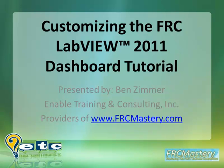So in summary, in this video, we talked about how to modify the robot project to put whatever information you need into the dashboard data type. Recall that in order to do that, you needed to modify the data type def, as well as make changes to the actual dashboard data sub-VI, which is writing that information in. And then we learned how to create the dashboard project and make the necessary modifications there. First, to refer to the proper data type so that it takes the same type def that's being used in the robot project. And secondly, how to extract all the information that you have added into that data type and modify the code so that it displays it in indicators.